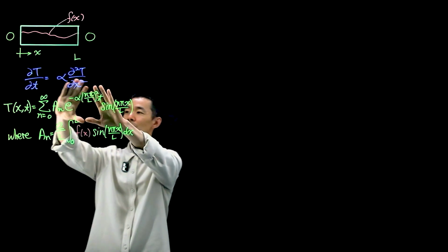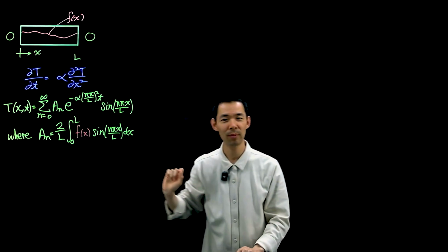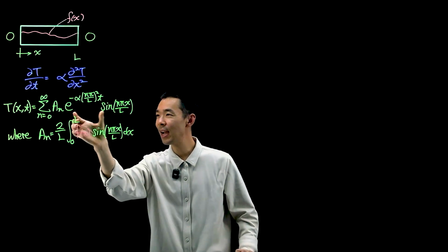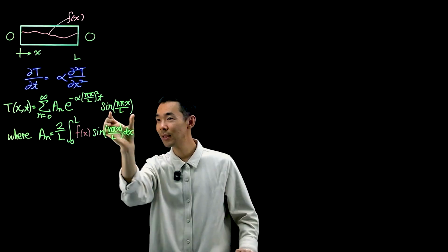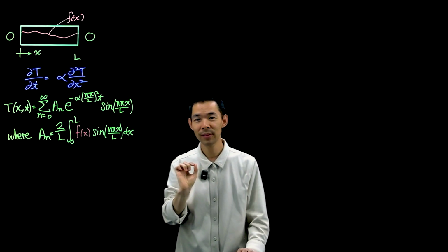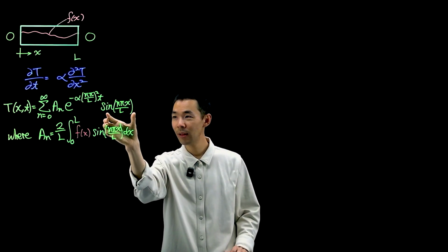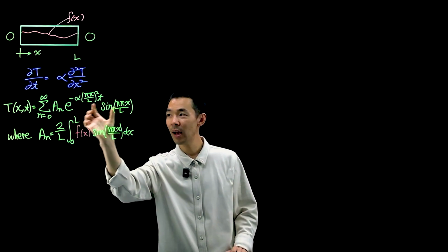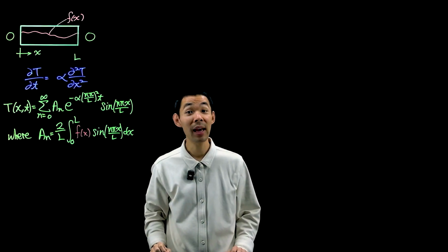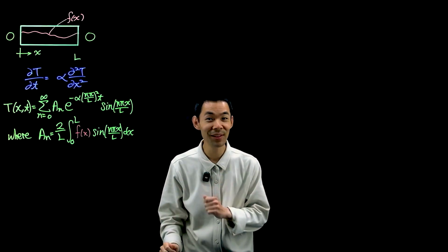And if you look at the structure of this temperature profile, ignoring the summation for the moment, you have an exponential decaying function times a sine. Sines are waves. So fundamentally what it's saying is I'm going to put in a wave, and for that particular wave, I'm going to see if it decays or grows or what happens to that wave. Let's consider the following.